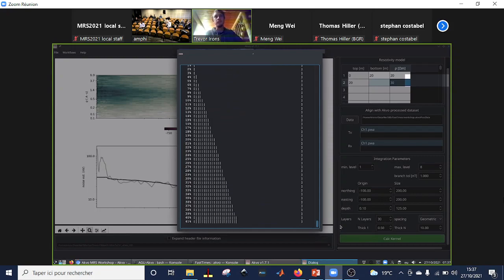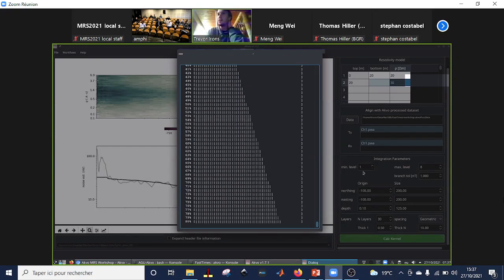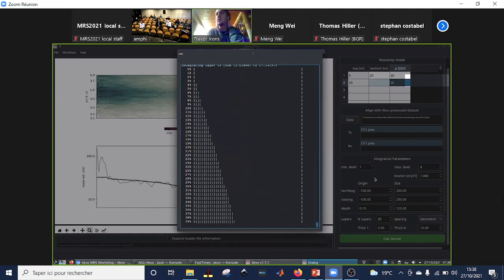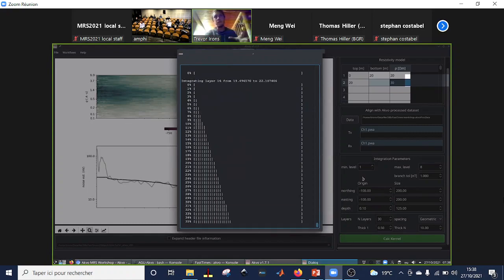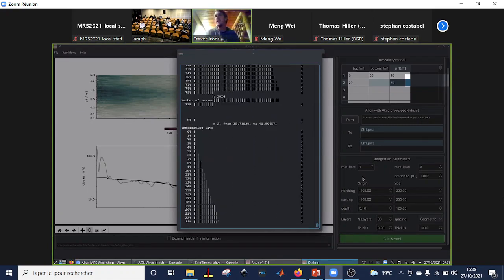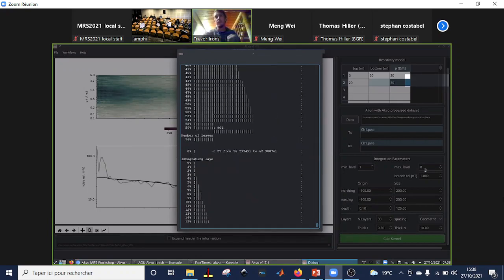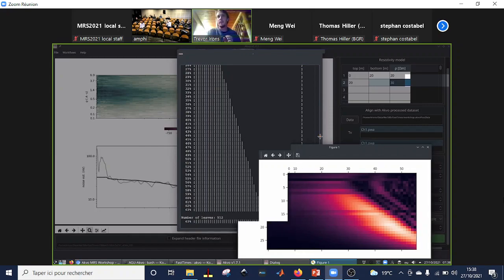And the shallower layers take a little bit longer than the deeper layers. So, depending on how exact you want to get this quadrature or this Octree, you can tell it basically how good of a solution you want. So you can say, I want this minimum level, make sure you split the Octree into at least 8 different sub blocks. And then the maximum level is only refine down to a certain level here. This was pretty quickly done.